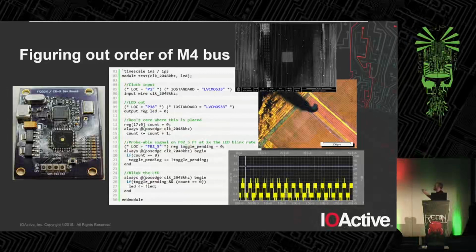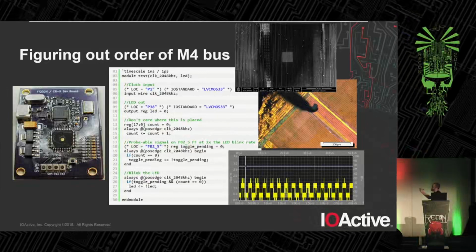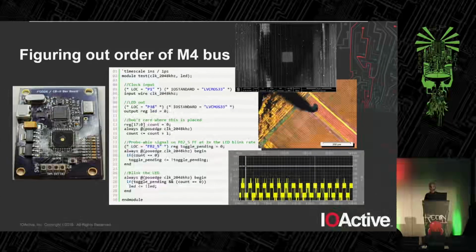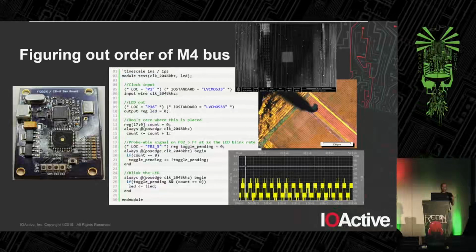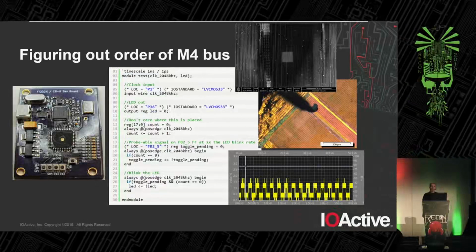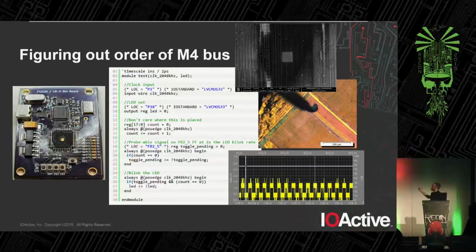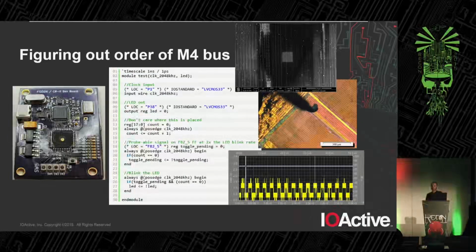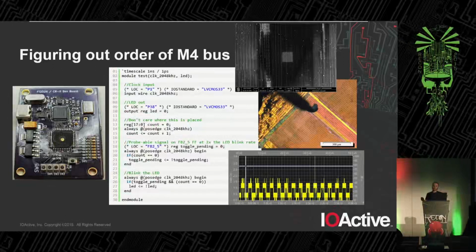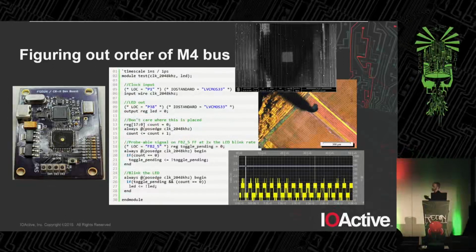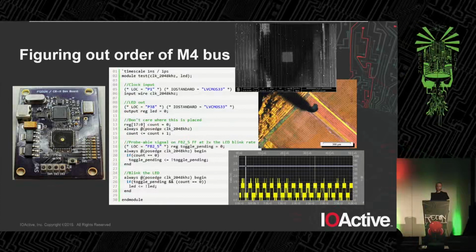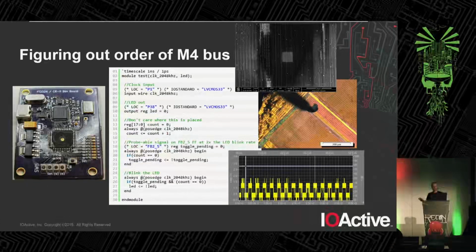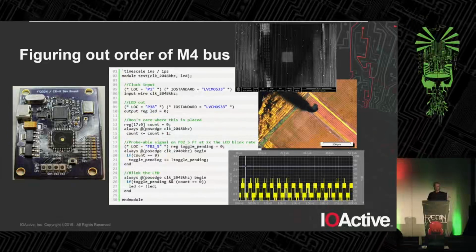Here's the code I'm using. It's just a counter going from a 2 megahertz input dividing down to, I believe, a 2 hertz LED. And then I have one signal before that. So 4 hertz is on a specific flip-flop that I've constrained the tools. I'm like, okay, here, function block 2, macro cell 5. So let's see. If we put a signal on function block 2, macro cell 5 that's supposed to be 4 hertz, and we've got a probe pad on this signal, is it a 4 hertz square wave? Oh yeah, it is. All right, our guess is right.